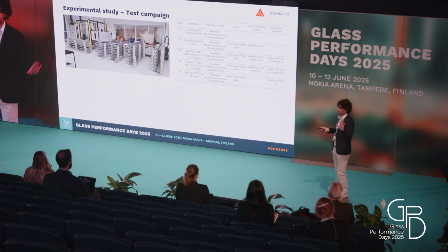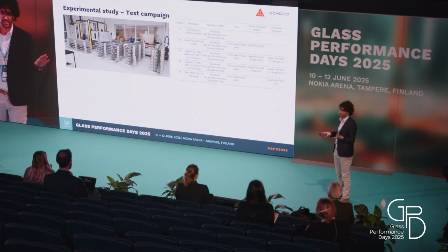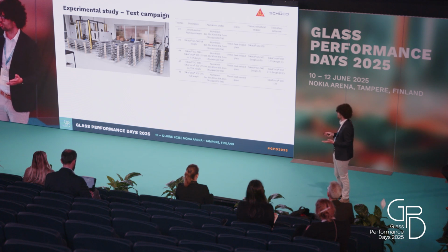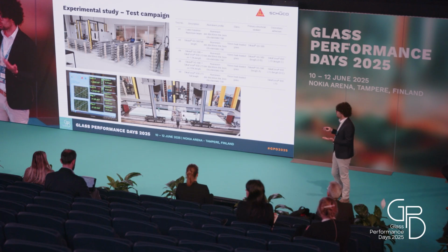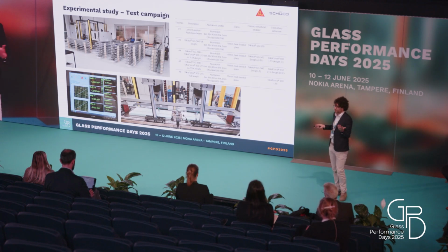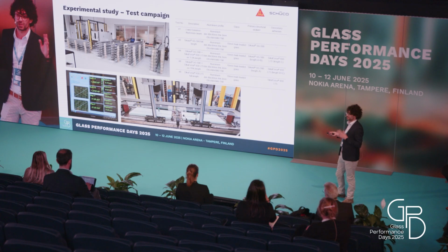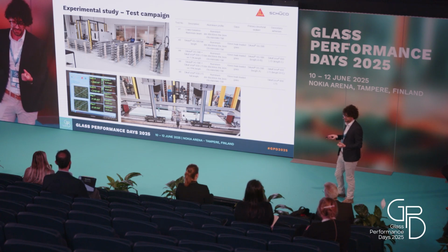And then just for an experiment, a theoretical study, we also did some beams with this secondary adhesive on the full length. But this was purely for a scientific study, not for real application. So we performed a long series of 4-point bending tests to measure the deflection of these beams.